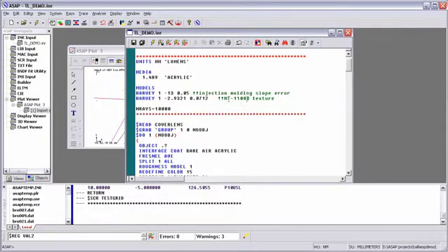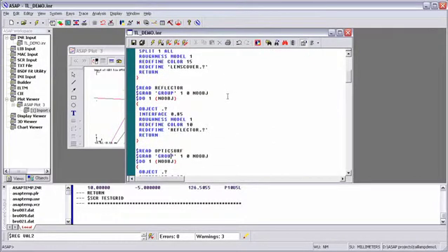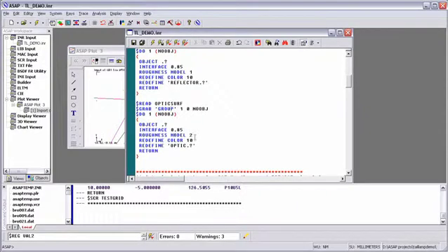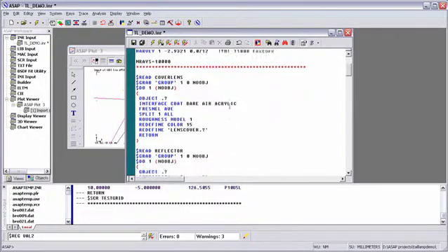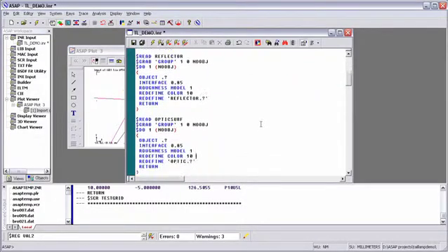The other thing I've set up in this particular file is a texture. For those of you that are familiar with injection molded parts, a lot of times they'll put on something called stipple or Mold-Tech finishes, and in this case I've simulated that reflector using that texture. If I wanted to find out what the performance is without that texture, I simply have to change my model back to just the bare molded slope part, and I could rerun my simulation and have that result.